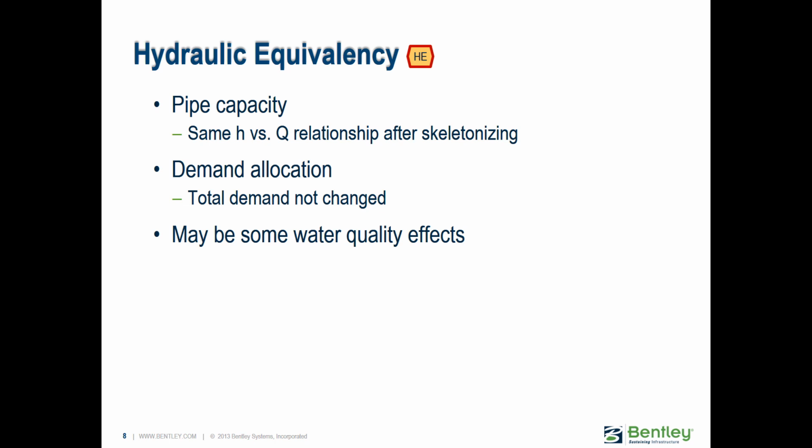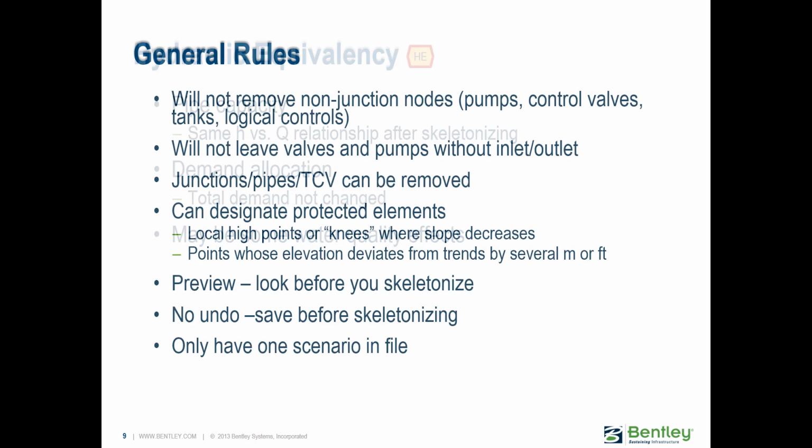Now, one note here on water quality effects. Hydraulic equivalency doesn't necessarily apply to water quality, so there could be some effects as far as water age and tracing of constituents, but usually you'll be dealing with a more complete, full model if you're doing water quality. So we're really talking about Hammer and transients here.